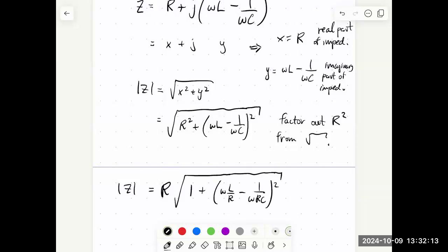Let's just notice something here. R times C. That's our RC time constant when we were talking about charging and discharging capacitors. So I know R times C has units of seconds. Omega is a frequency, it's inverse seconds. So the product, omega times RC, is dimensionless. I like that. If you can work in dimensionless quantities, they often have some kind of physical significance to your problem. You just handed in an assignment where you analyzed the LR circuit, and you should have found the time constant L divided by R, or you said gamma was R over L. So this has units of seconds times omega, which is 1 over seconds, and so this is also unitless.